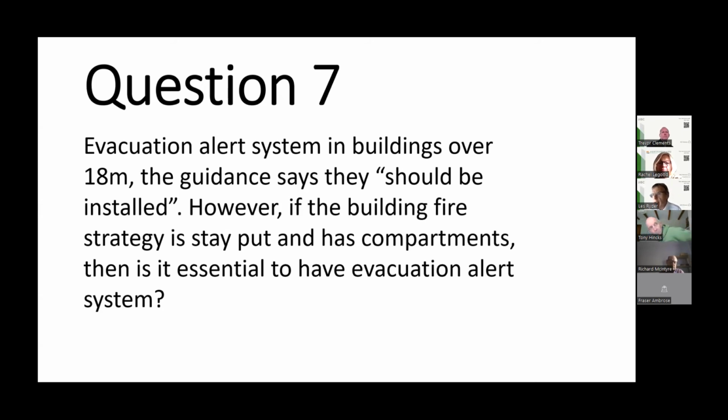in the unlikely event of a fire occurring with a building in this condition, it should work well. But having said that, if it's a relatively new building, the only area where it wasn't particularly well controlled was the external wall, and the external wall now is being well and truly tied up by Regulation 7. So tie the external spread up with Regulation 7. And now we have the intention to have an evacuation alarm system in accordance with that British standard. Then I think all of the major lessons from Grenfell will be learned. First of all, the external wall, and second of all, the fire authority having the ability to evacuate the building if they need to do so.